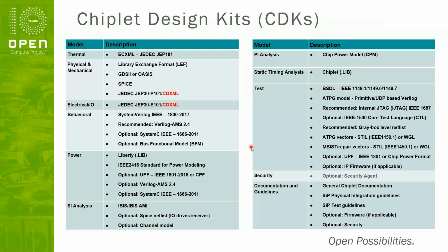Quick question. Those tests will be pre and post assembly, the patterns? Well, the presumption is the chiplets would be tested at wafer sort and delivered to the integrators. So really, these are the patterns that would be required post assembly. We didn't see a need to retest the part that's already been sorted from the vendor.